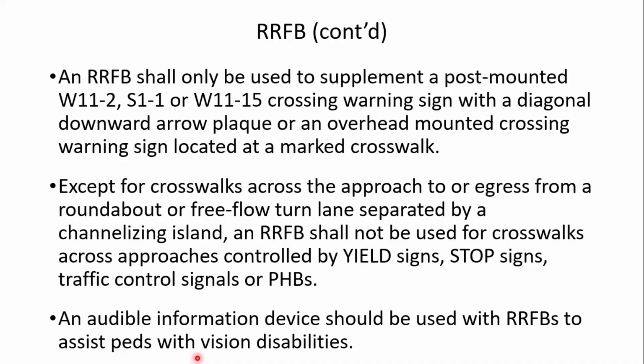And also, we need to have an audible information device with the RRFBs to assist pedestrians with vision disabilities, to let them know that this is not a standard red, yellow, green traffic signal. It's a flashing warning device.